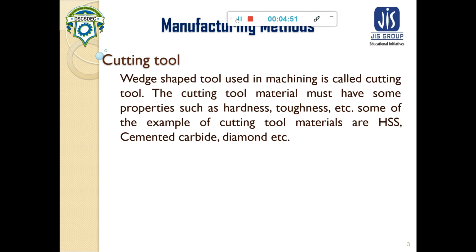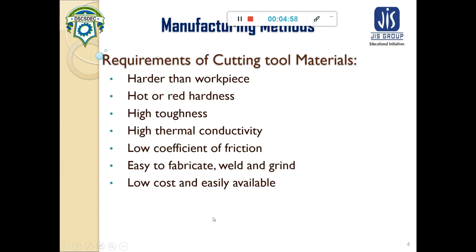Now we will see the requirements to be a cutting tool material. The cutting tool material should be harder than the workpiece. Hot or red hardness should be there.